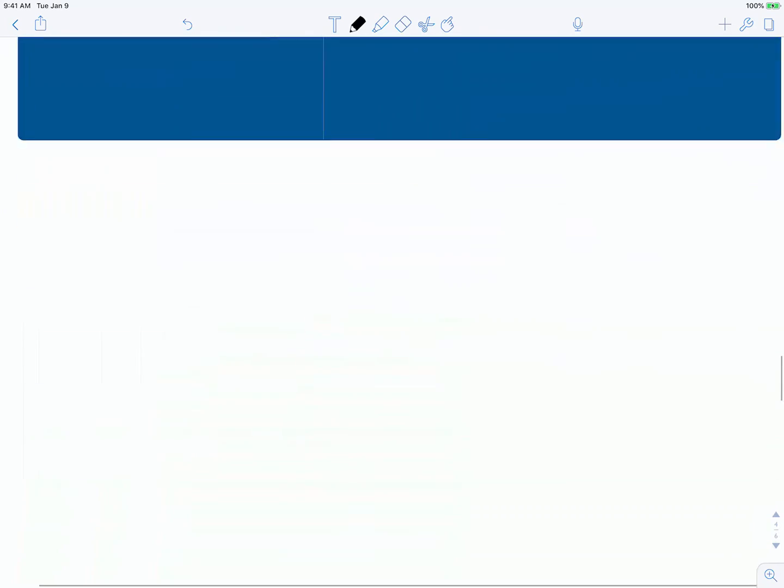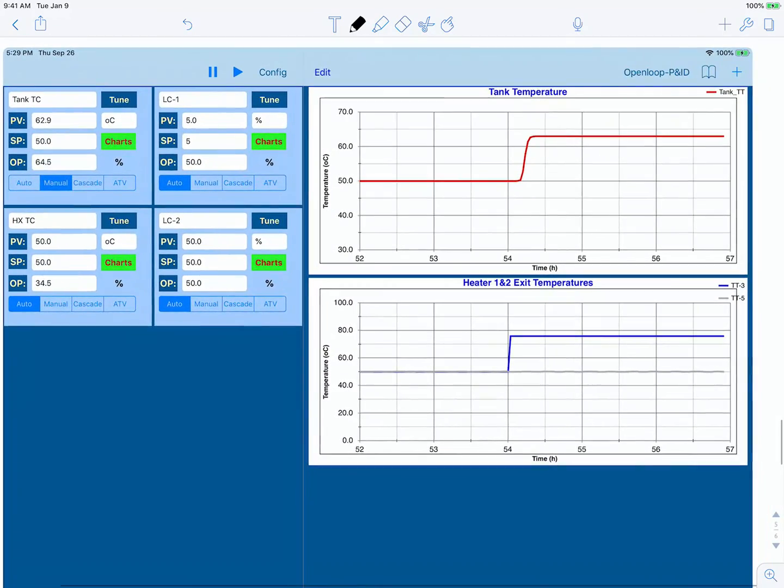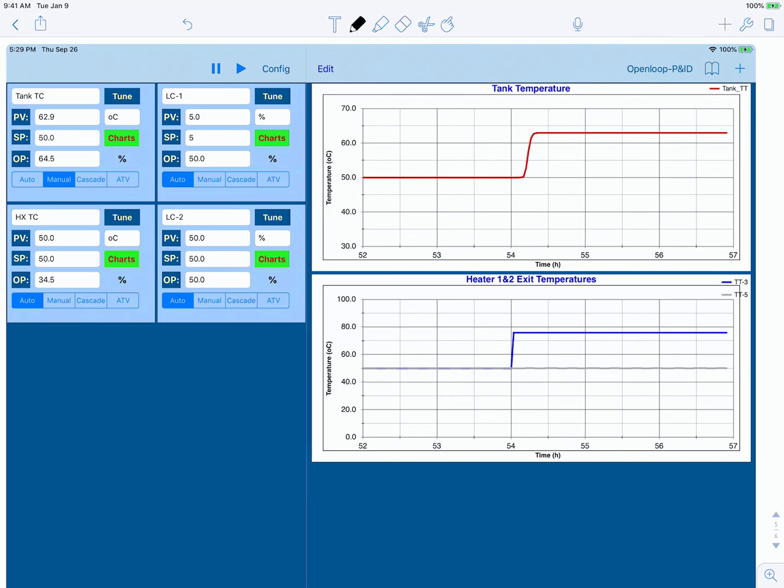And the final case that we looked at was when we had a short time constant here, but we arranged to have the long delay in the ion exchange column, so we have a long dead time. And the dead time to time constant ratio in this case is going to be 0.2 divided by 0.018, and that is actually 11. So a very large ratio.